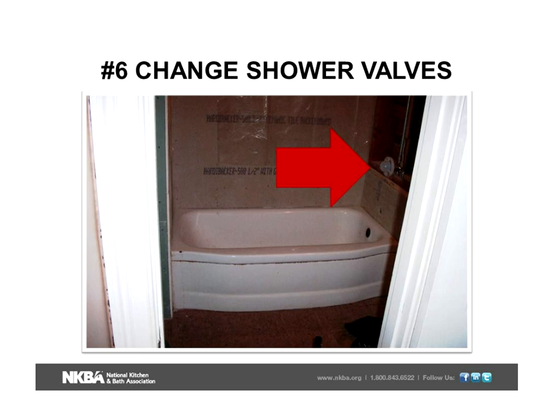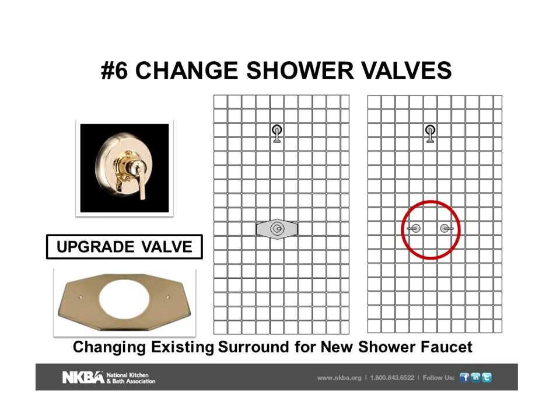But now's the time. So not only replace an existing two-handled one, but also you want to replace the actual valve if it has much age on it. A lot of changes have been made, and this may be a good time to change that finish at the same time. Now, if you do encounter the two-handled unit, then it is possible to go through the shower side of the wall to make the swap out. And to patch everything up, a rather large escutcheon plate can go back in.